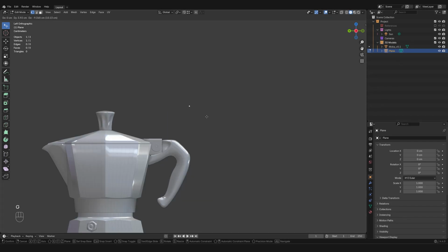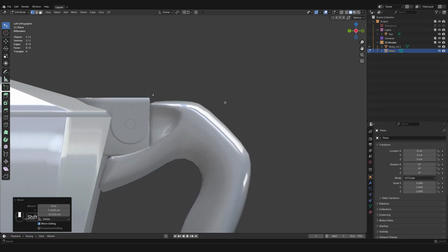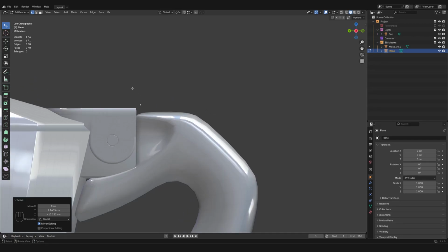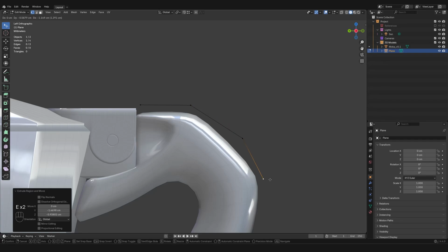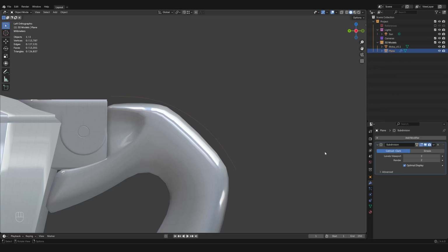And so you saw me take this approach when I was 3D modeling the handle. So I created for myself a clean single vertex. And from there, I pressed E to extrude it. And now I have an edge. And then again. And so that is how I ended up creating the curve. Then you saw me duplicating and transforming into faces as I went about constructing the handle.